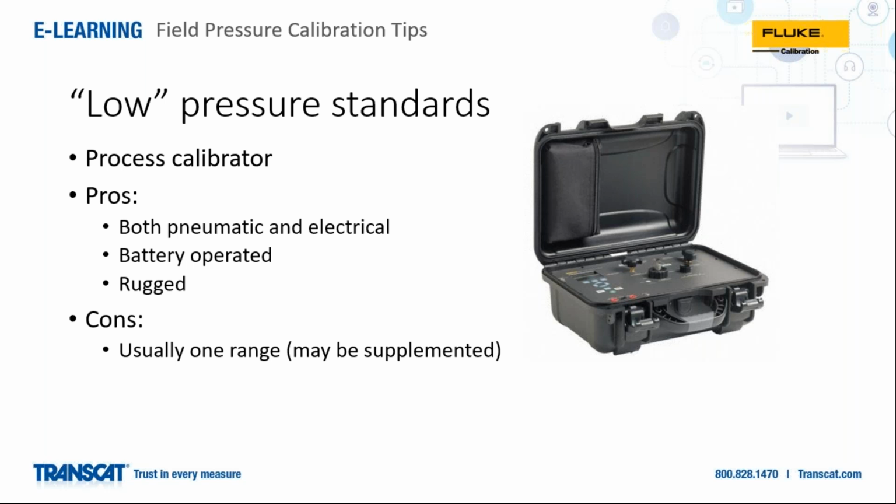Another fluid that we use on the Fluke calibration side on some of our higher end standards is a synthetic fluid called Sebacate. It's really a plasticizer, used to soften plastics out in industry. But we chose it because it has pretty good behavior as a calibration fluid. It's very benign. It's even used as an ingredient in makeup and sunscreen.